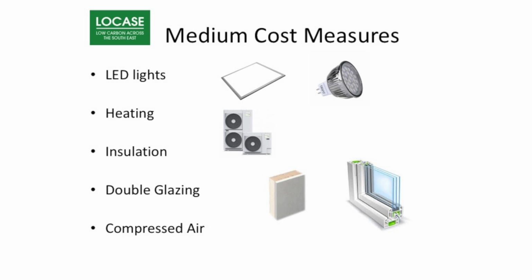Moving to insulation, an uninsulated building won't retain heat, and the heating system will be working to make up for the losses, leading to higher energy bills. So it's always a good idea to start with insulating your walls, your roof, and then using double glazing for your windows. That way you won't be heating without a result.